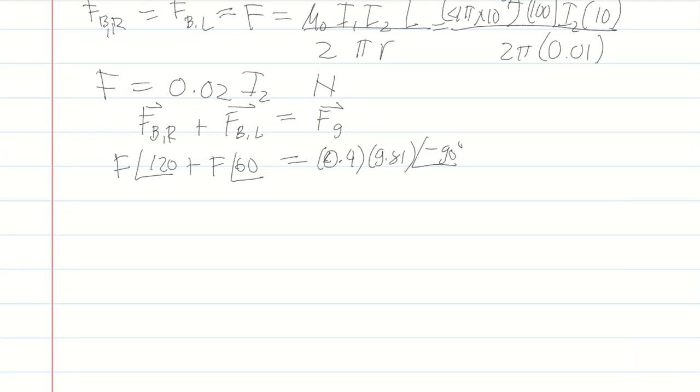So to solve for F, we need to convert these two into rectangular form. They are in the polar form. We cannot just add them in polar form. So we need to convert them into rectangular form. How do we convert them? So remember, from polar to rectangular: R angle theta. So this is polar. If we convert this one into rectangular, it should be x plus jy, where x is equal to r cosine theta and y is equal to r sine theta.